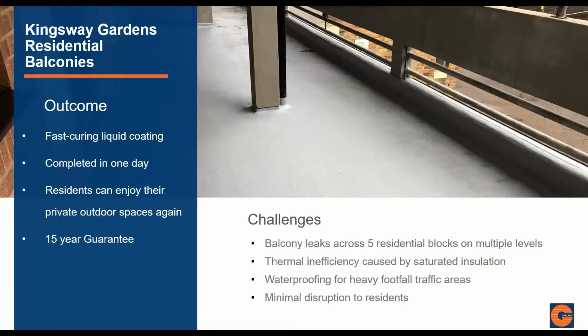Again, we were very much up against it in terms of minimal disruption for the residents. They use their balconies frequently for access. So we had a very limited period to get this installed. So we used a fast curing product, where each layer cures within 20 to 40 minutes. So the whole system can be done within a day. Therefore, we're helping the residents in terms of getting in and out, and also providing them a new waterproofing system that's homogeneous and getting rid of all the issues they've been experiencing.